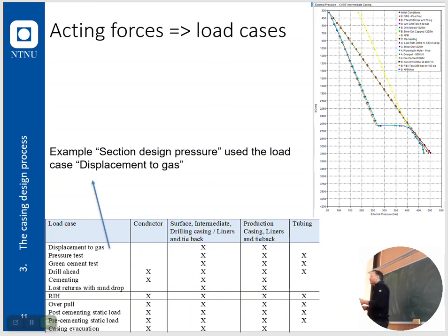When formations collapse, typically shales and typically sagged weight material, your casing is as stuck as if it was cemented. And that's why P&A is very hard when you're cutting the casing and trying to retrieve it. It's stuck, and you have to cut small sections.